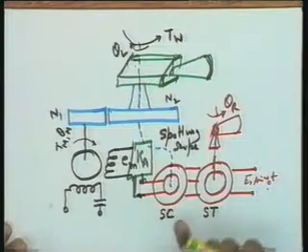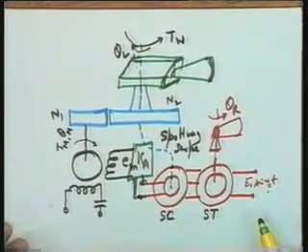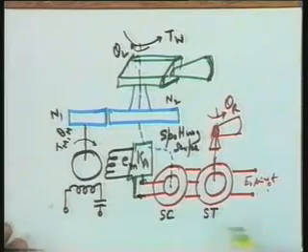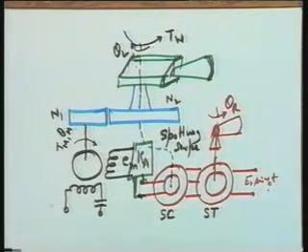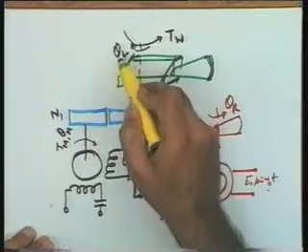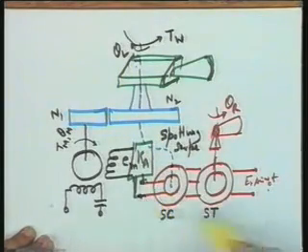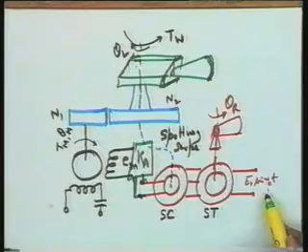So if you see the basic definition of a modulating device, your synchro device is acting as a modulator, because it is accepting a DC signal, theta_r minus theta_L, and giving out a modulated signal whose frequency is given by omega_c.